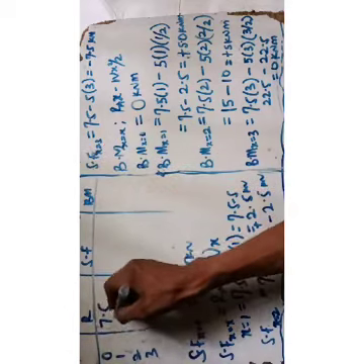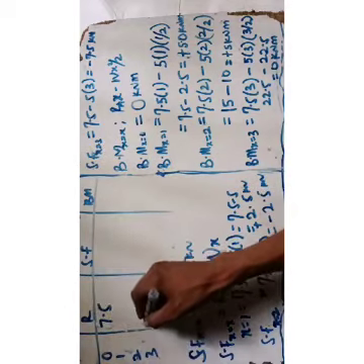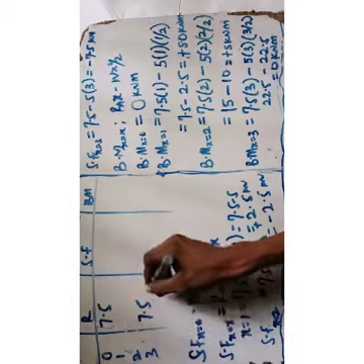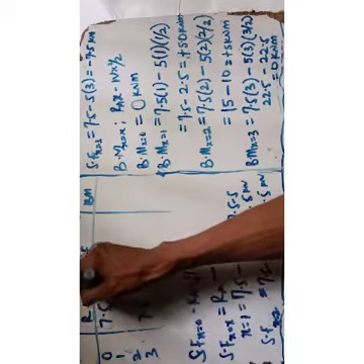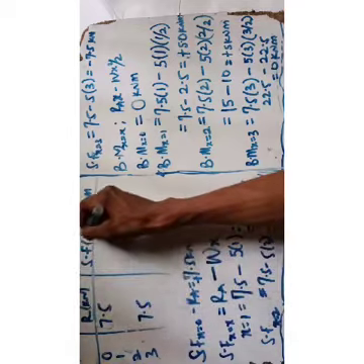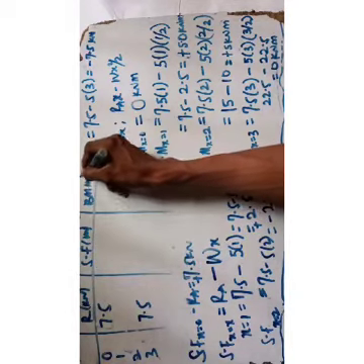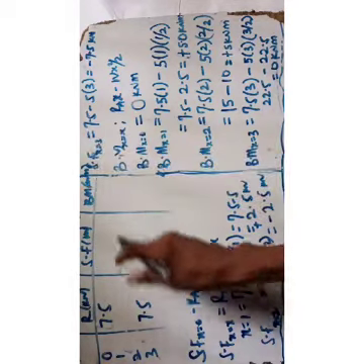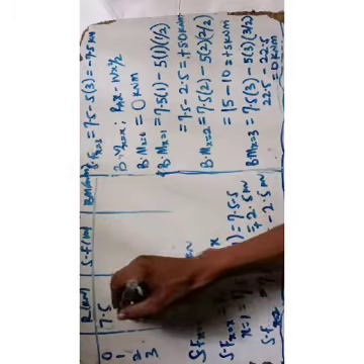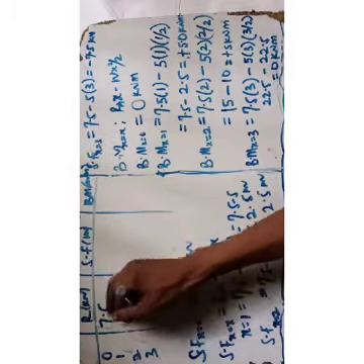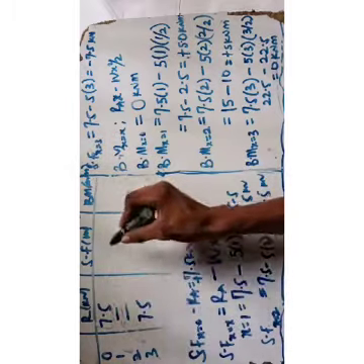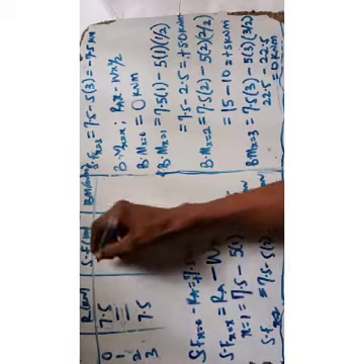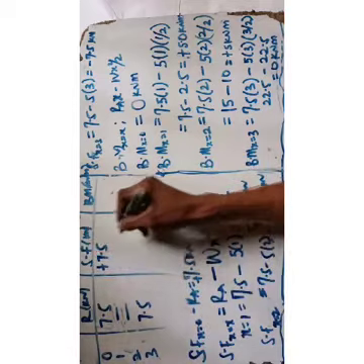At 1, at this they correspond, and you see it at the last part as 7.5. That is kilonewton. That is the reaction. This is kilonewton as well. Why is this one kilonewton meter? So, the shear force at 0 we find out is 7.5. That is plus 7.5 kilonewton.